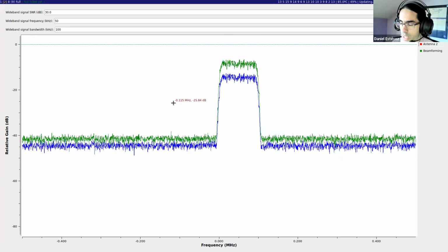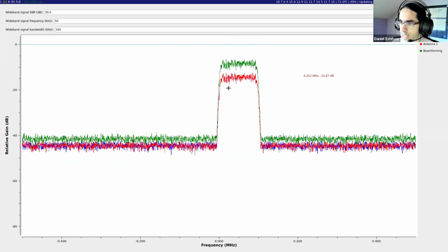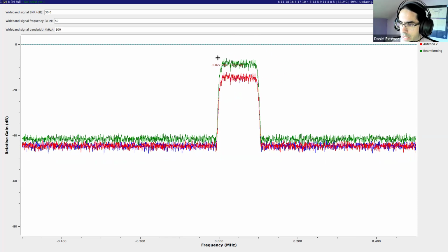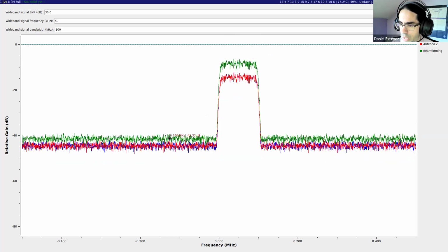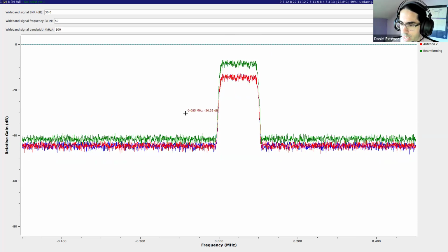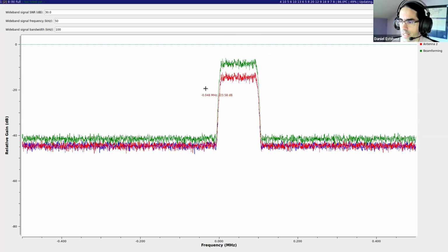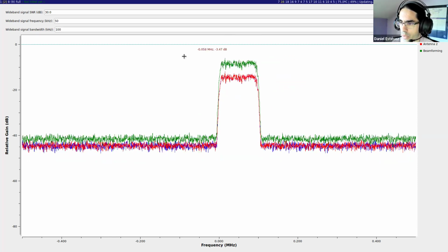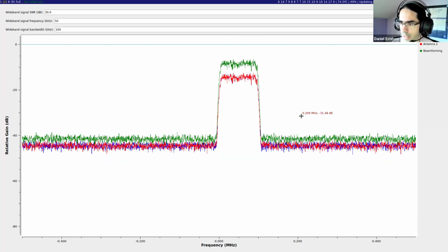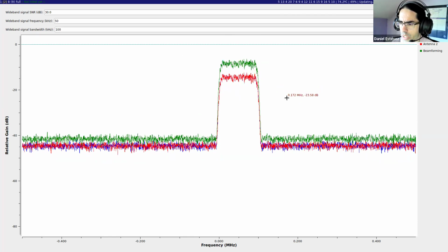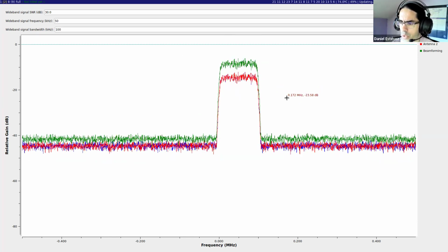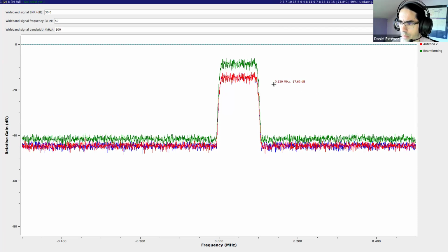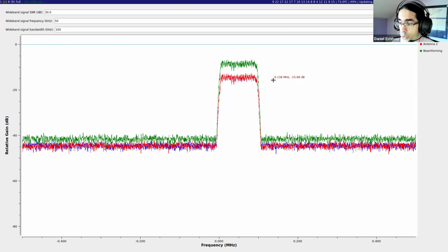So to sum things up, we have two antennas. We are adding the signals from two antennas, and the signal itself increases by 6 dBs. The noise increases by 3 dBs only. So the difference, 6 minus 3 is 3 dBs. That is the signal to noise ratio that we gain by doing this beamforming combination. And this is what we would expect from a physical point of view, because the SNR increase is 3 dBs, or a factor of 2.